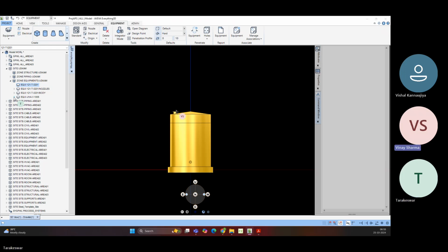In that case, you just connect that pipe and then do the piping as per your process compatibility or your space availability, because you need to see everything. For example, if you are doing the routing of the piping, you can't create a wall here. If you create the wall here, how will a person access it? For that, he needs to prepare a separate platform. I'm just giving an example.